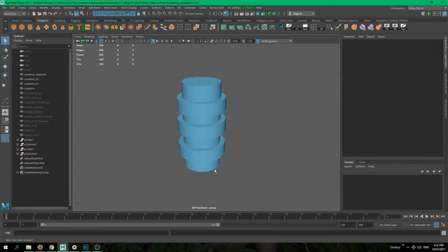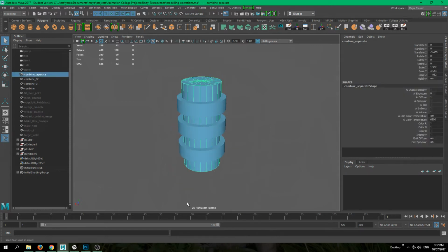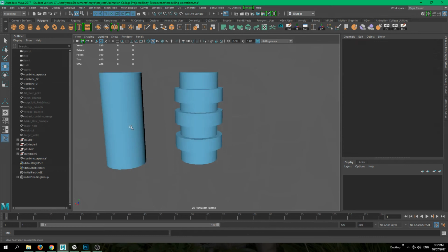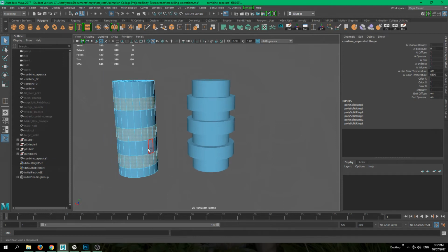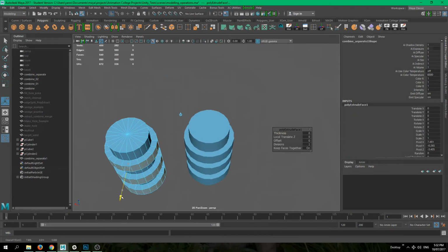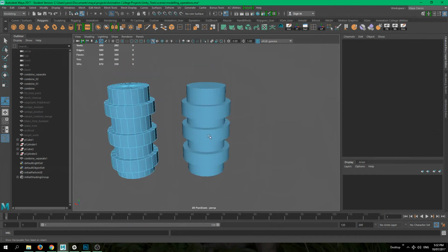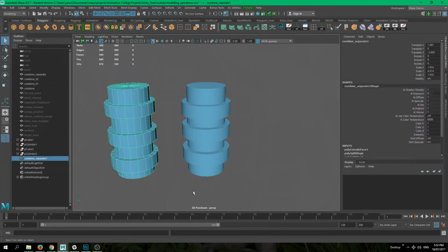So when you start modeling, your initial idea will be to try and connect all elements together. So for example, the same type of shape could be achieved by me grabbing this cylinder. I will just duplicate it really quickly, creating a whole bunch of edges with my Insert Edge Loop tool. And then you can extrude from here. And of course you will be getting a similar result.